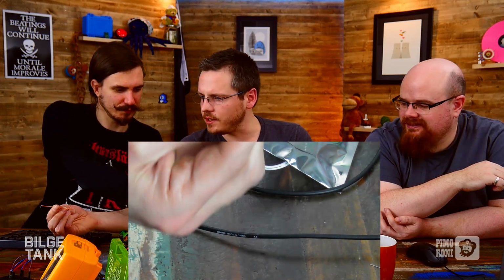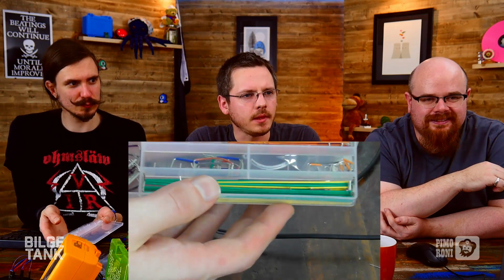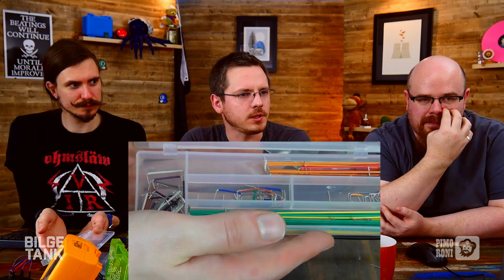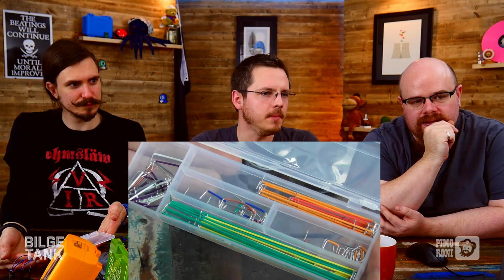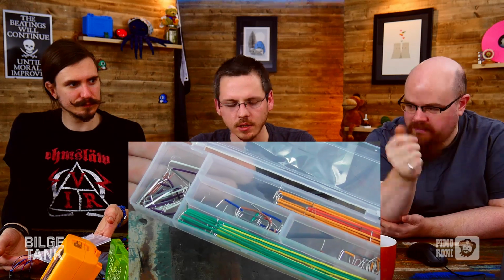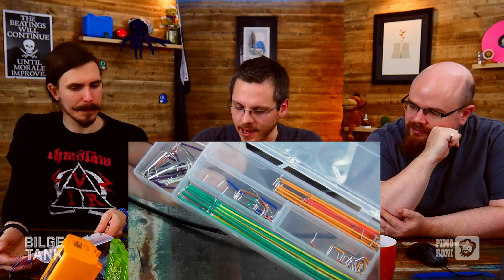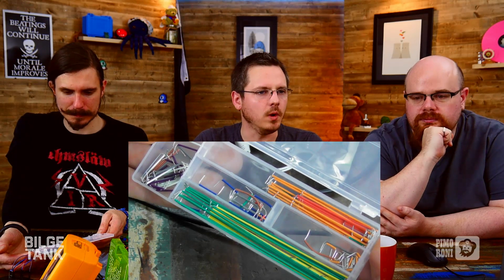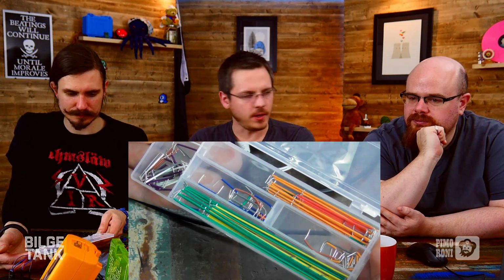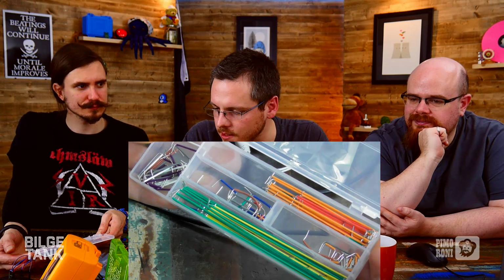Show the tray, Phil. Show the tray. They're dead handy, and the ends are preformed down. So you just find the wire that's the right length, and I've used them all over this breadboard. It saves you having to strip, and they're bent to the steps of the breadboard, aren't they? You can pretty much always find exactly the wire you want to keep it flat against the surface. Otherwise, you end up with a Franken circuit and wires hanging out all over the place.